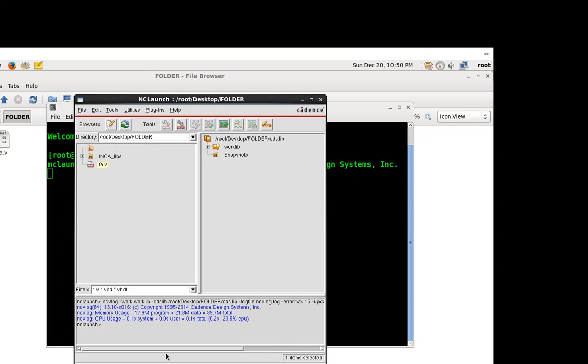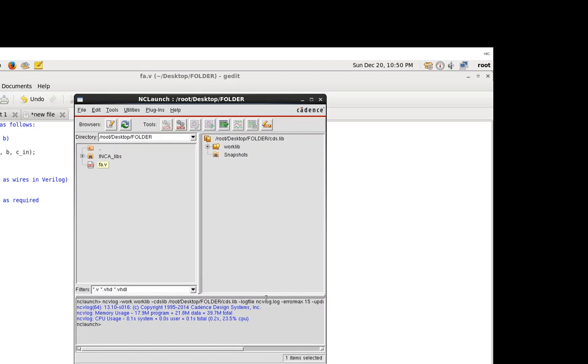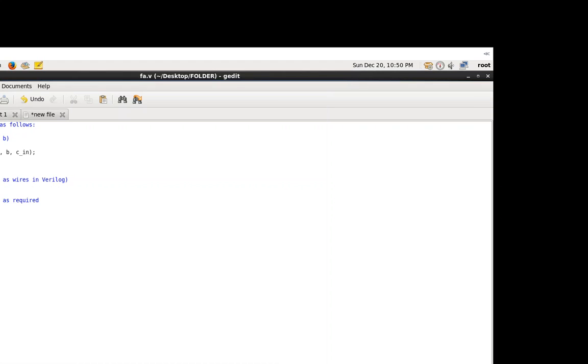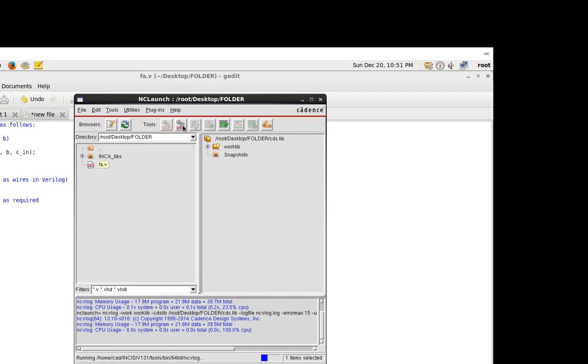And how do you go and correct the statement? Click on this file again, and it will give you some information about where that particular error is. So you search for that line in the Verilog file, make the changes that will correct the error, click on save, and then just come back here and press this button again. You don't have to start the tool and all again.